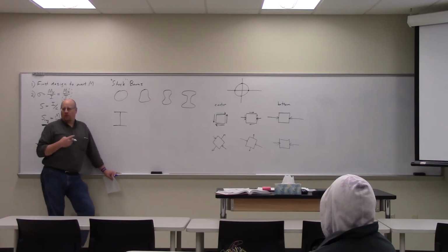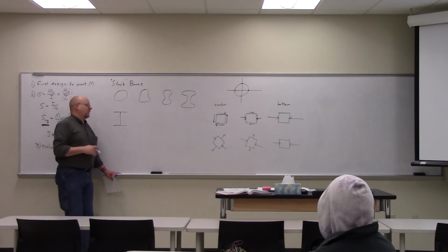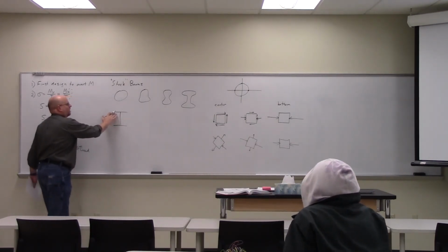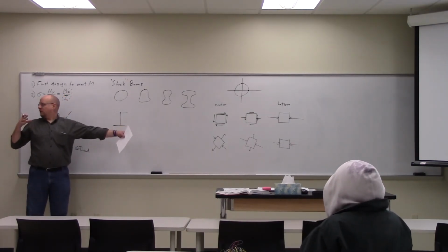Like I said, it doesn't go through nice smooth shapes like this. They'll roll it flat on one side and they'll roll it flat on the other. And they anneal it in between to soften it back up again. We'll talk about a lot of that material science. Anyway, the point is you end up then with a single monolithic cross section that is some length, depending on how much ingot you put in the first place.